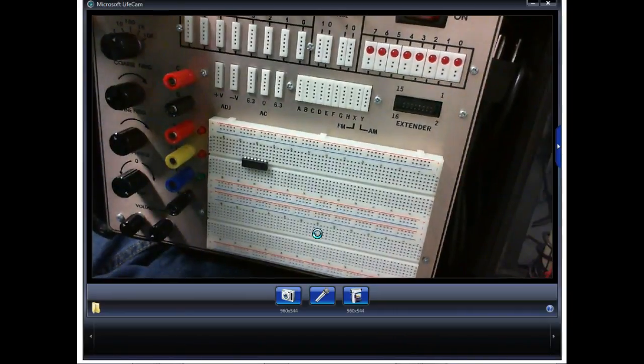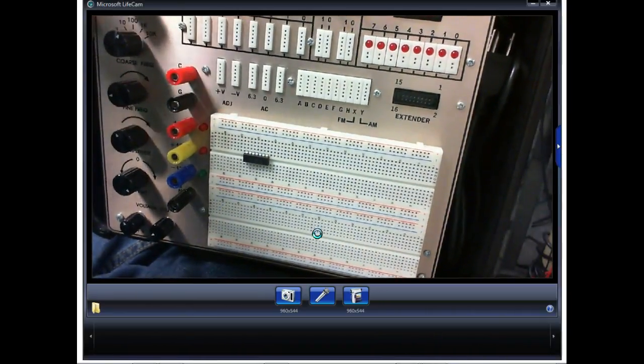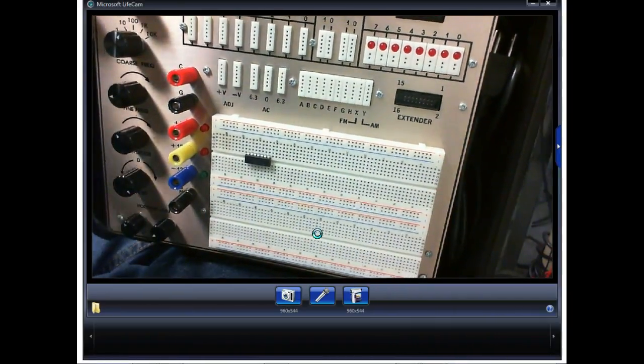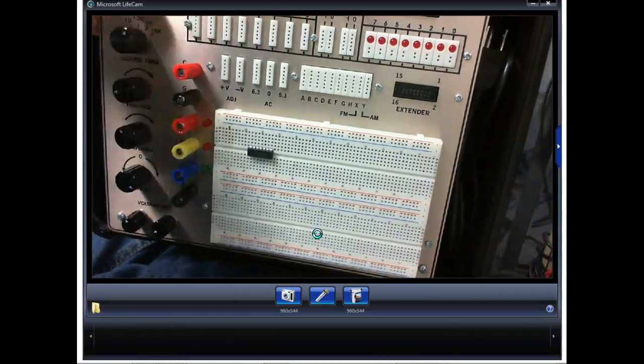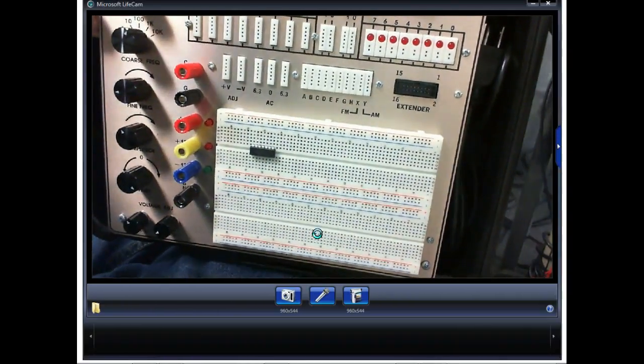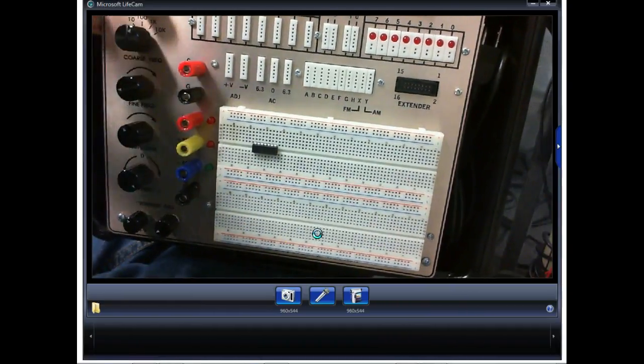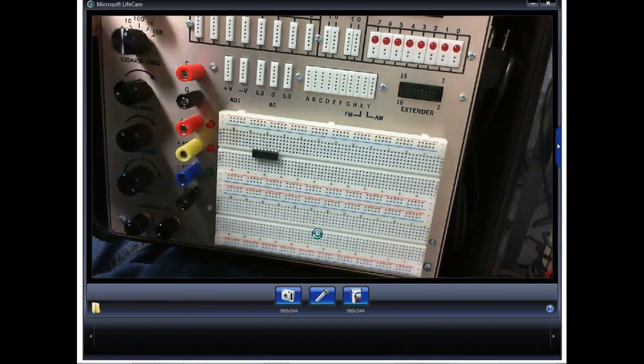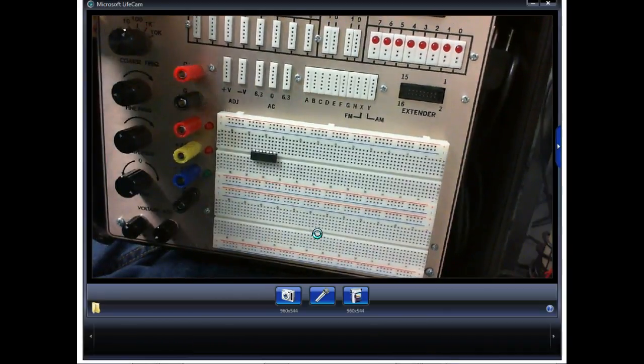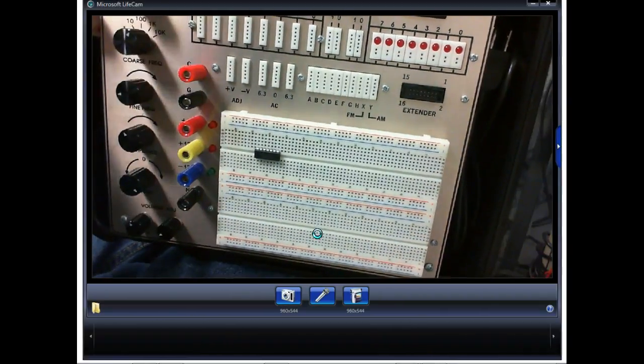So you're supposed to know, okay, I've got an AND gate, and I'm supposed to have all highs to get a high. If you don't give me all highs to get a high, then either the gate's bad or I've got it wired up wrong. We don't tear circuits down here and rebuild them, because you miss out on a perfect opportunity to troubleshoot.